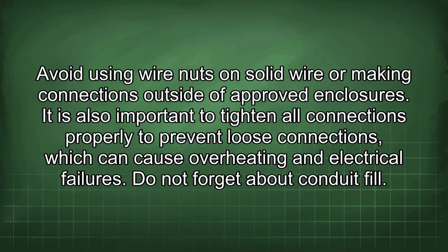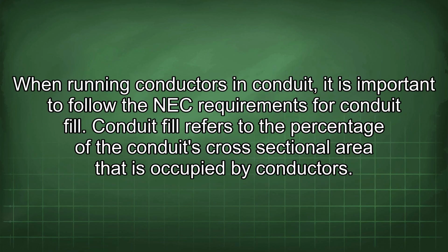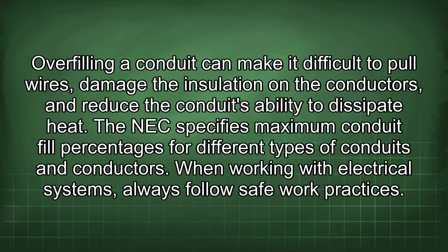Do not forget about conduit fill. When running conductors and conduit, it is important to follow the NEC requirements for conduit fill. Conduit fill refers to the percentage of the conduit's cross-sectional area that is occupied by conductors. Overfilling a conduit can make it difficult to pull wires, damage the insulation on the conductors, and reduce the conduit's ability to dissipate heat. The NEC specifies maximum conduit fill percentages for different types of conduits and conductors.